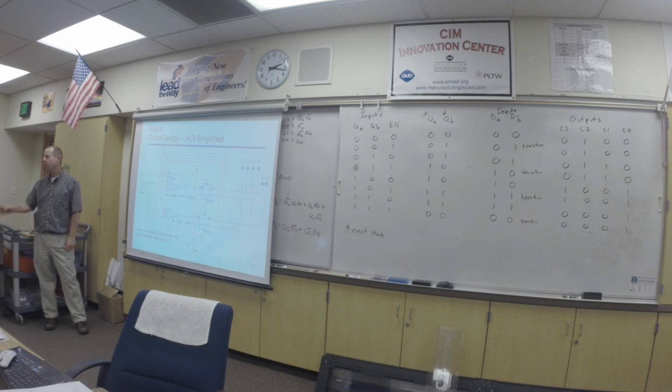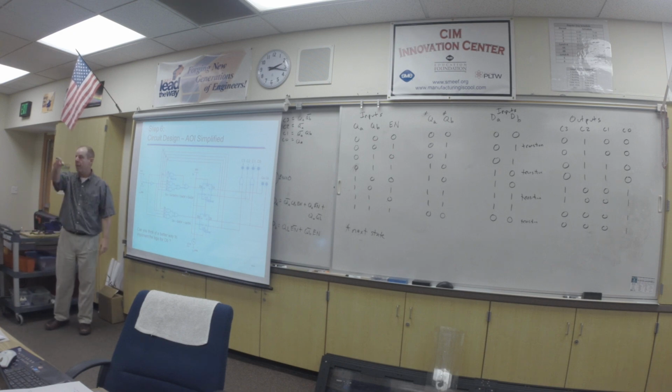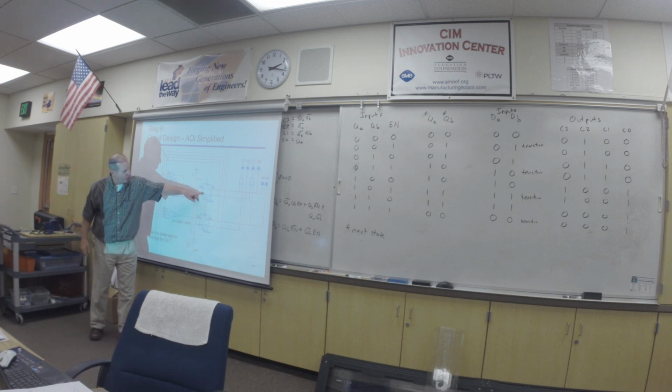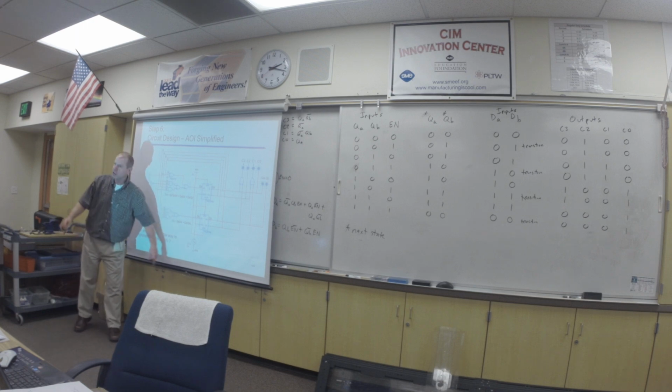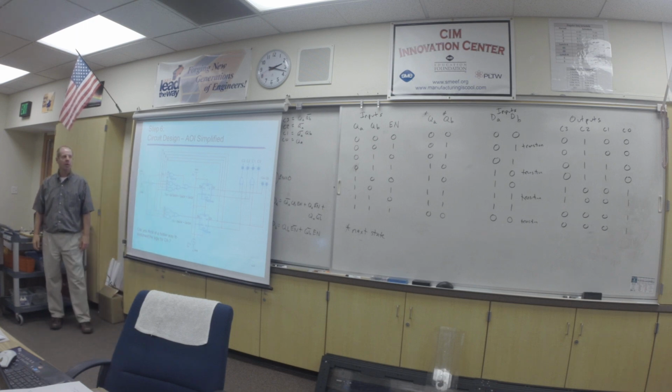Okay? Question, David. So when you're saying it's cycling through, the clock control, how fast? Yeah. Thank you for bringing that up. You'll notice that the clock inputs in the two flip-flops, I forgot to mention this, are both synchronized to the clock. This is a synchronous counter. All right? So it has to be synchronous. If it isn't synchronous, if it's asynchronous, nothing's going to work. It has to be synchronous to get that signal to trigger each time. And they just got it at 20 hertz. You can make it 50 or 100, however fast you want it to go.